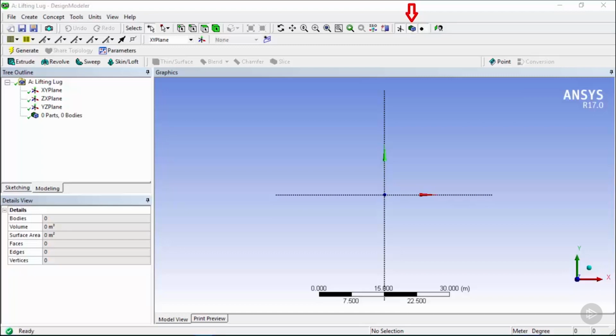If you turn off the 3D model, the plane is turned on automatically. Then next we have the display points, which allows you to toggle between displaying the points generated by point features in the model or not. And finally, we have the Look at Face, Plane, or Sketch button. This button centers the display on the currently selected face, active plane, or active sketch.